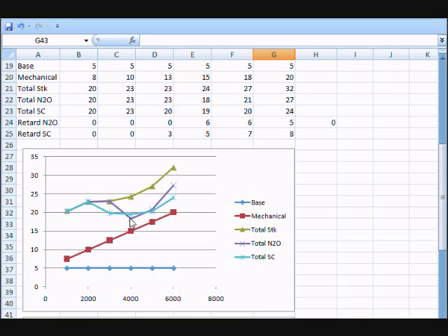And all of the racers know this when they use nitrous, especially if you're using a very large shot of nitrous like a 200 shot or 250 shot. When you start out that run and you hit the nitrous, the first initial hit, you might get 250 horsepower, but as you go down the track, the bottle pressure will drop slightly because you're using such a high flow rate of nitrous, and so the volumetric efficiency will start to drop too, and so you can add a little bit of timing on the top end, and the car will still be safe because the mixture is less dense and it can take a little bit more timing, and that'll give you a little bit better times.